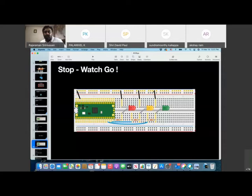So for each of these LEDs, you are going to put a grounding also. So you are connecting a total of 4 jumper wires. These 3 are grounding the LEDs. The other one is grounding the Pico board. So there are 4 grounding here, and then 2 jumper cables which are connecting to the lines where you have the resistors connected. Then you have 3 LEDs total. Okay, so that is the overall circuit. So Akshay will show it through his camera.